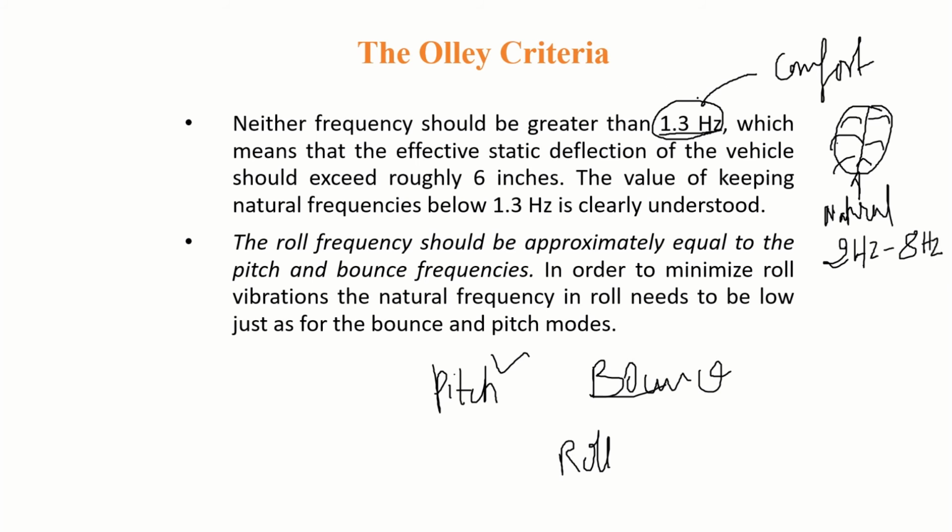So our forced frequency or induced frequency should be less than this or outside this range. That's very important. This can be achieved, and then only you will get the comfort. To achieve that, the pitch and bounce centers should be as specified.